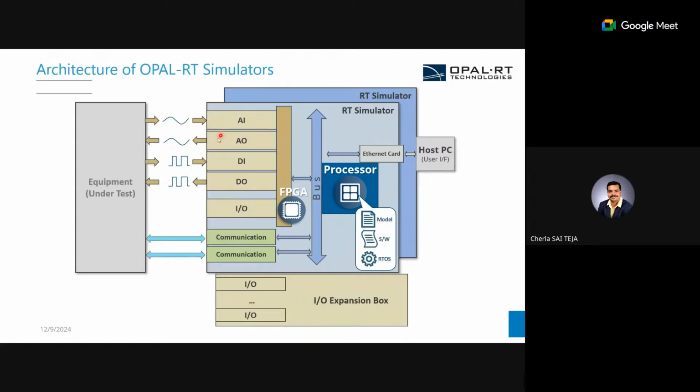And it's the same for any application actually. The device under test can be anything. The appropriate plant should be running here, and by using the IO channels, today I can use it for an FOC control of a PMSM motor. Tomorrow we can use it for DTC control of an induction motor. So we can use the same simulator for a number of projects. That is one of the better places for real-time simulations. It will help you to test and validate different control algorithms in a much faster way.